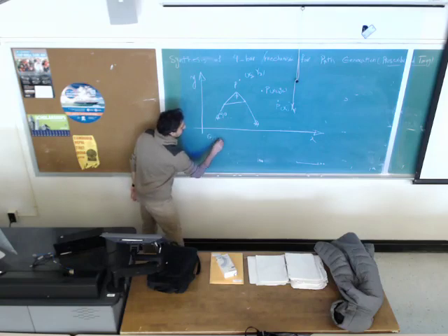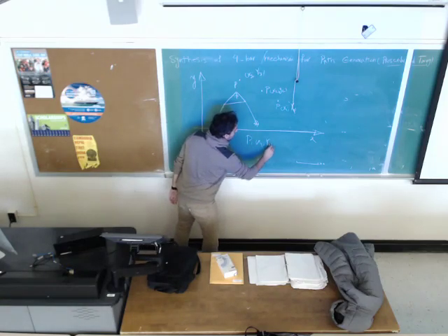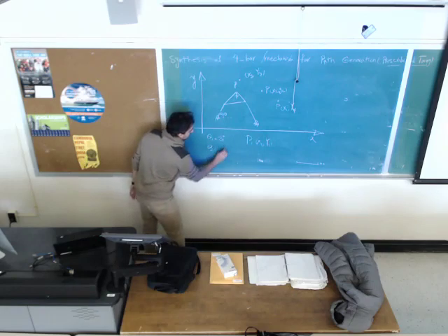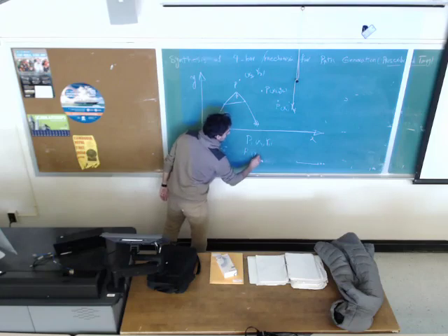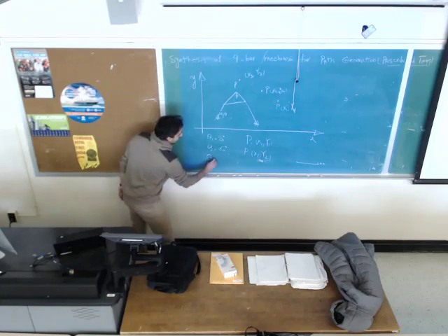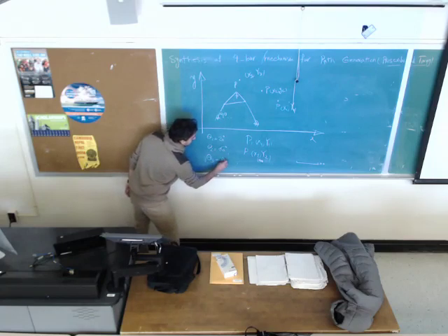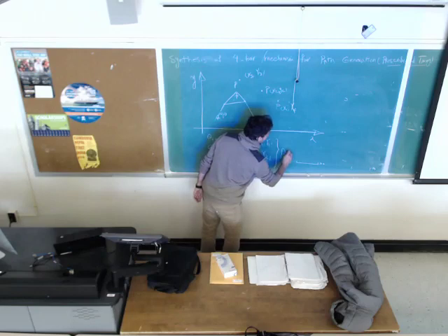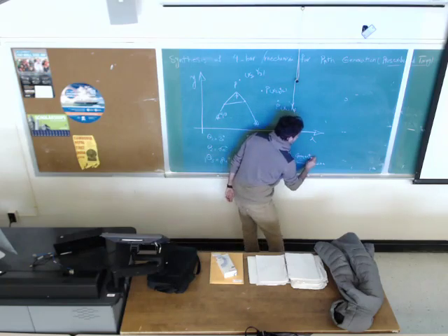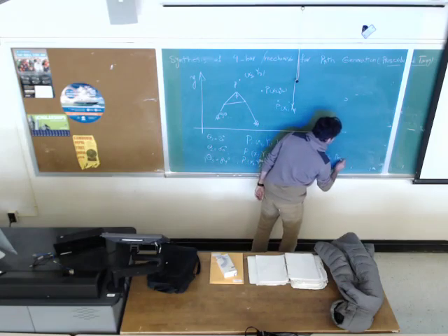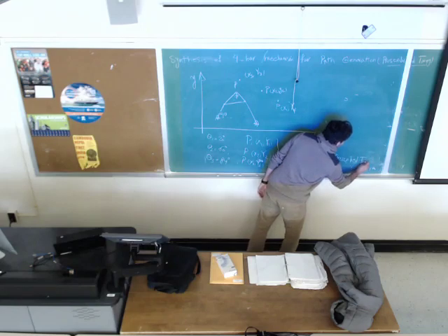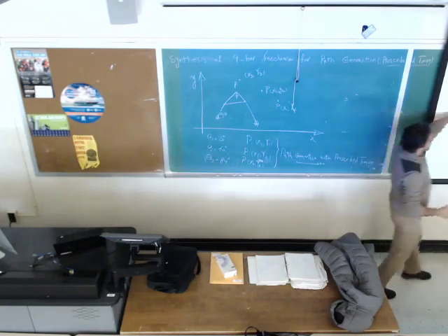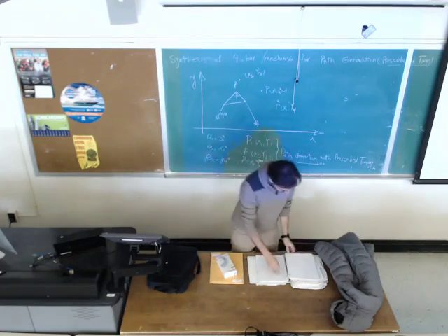What I am saying is, if you would like point P to be at x1, y1, and theta 1 is important for you, so you would like to have it at 20 degrees, then theta 2 is 60 degrees, point P should be at the second precision point, and when theta 3 is 84 degrees, you would like P to be at the third precision point. If this is the case, we call it path generation with prescribed time. So the timing is important for you. So in this lecture, we are gonna go over path generation with prescribed timing.